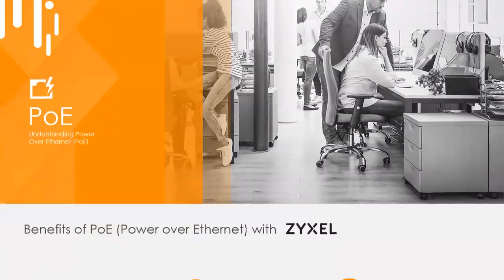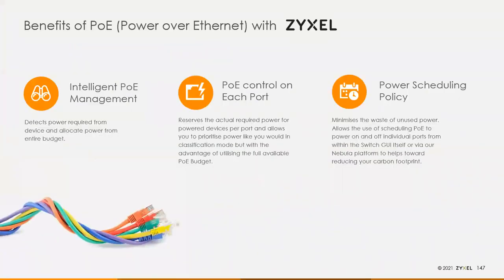So one thing we do a little bit differently on our PoE that not all of our competition has is intelligent PoE management. Basically, the way that the standards are based, devices classify themselves as class 1, 2, 3, or 4, and that determines how much power budget the switch reserves for them. Unfortunately, there are some huge jumps between those different classes.